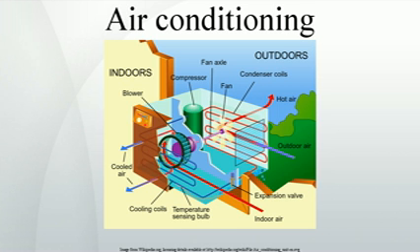By placing the condenser, where the heat is rejected, inside a compartment, and the evaporator, which absorbs heat, in the ambient environment, such as outside, or merely running a normal air conditioner's refrigerant in the opposite direction, the overall effect is the opposite, and the compartment is heated. This is usually called a heat pump, and is capable of heating a home to comfortable temperatures, 25 degC, 77 degF, even when the outside air is below the freezing point of water, 0 degC, 32 degF.